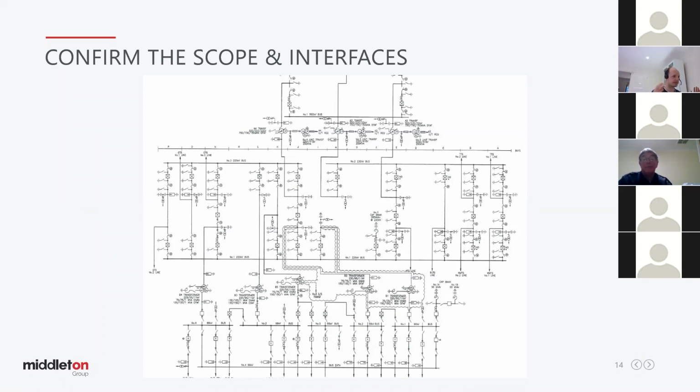So here I've just pulled up a random SLD, not quite so random, because we can see down here in this clouded area, we have two transformers, which are 220 to 66 to 11 kV, which are highlighted or clouded. And that generally means that we are changing or modifying this particular drawing to replace that equipment. So in our case, we're replacing two transformers, which are connected into these bays here. We are then connecting the secondary sides through to number 2 and number 1 66 kV buses.